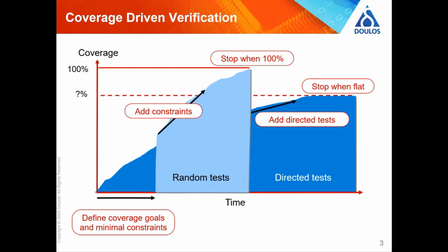So we're steering the creation of this random stimulus, and that's why we call it constrained random stimulus. So it's not just completely random, it's not just give me whatever you like, because there's no direction there. We'd probably still be as lost as we were. There's no guarantee that's going to give us better coverage.